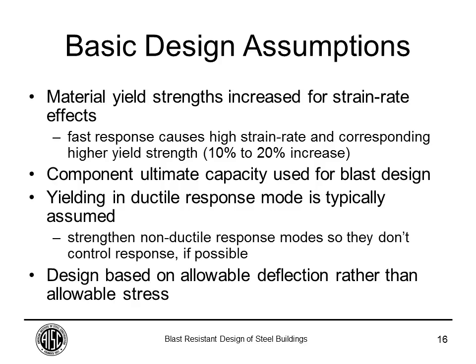Typically, we want components to respond in a ductile manner, so we try to make the connections strong enough to develop the capacity of the member. And finally, the design is not based on stress limitations, like moment capacity or shear capacity, but rather is controlled by the deformation limits, which we're going to see later are usually expressed in terms of support rotation and ductility ratio, which is a measure of the plastic deformation.